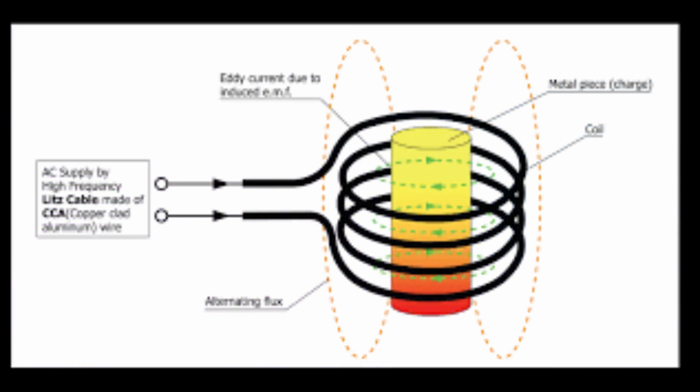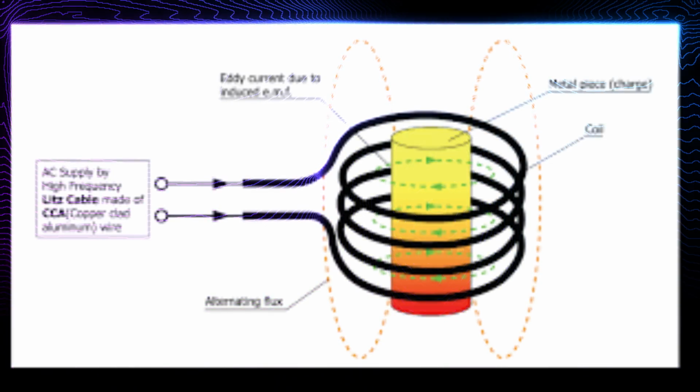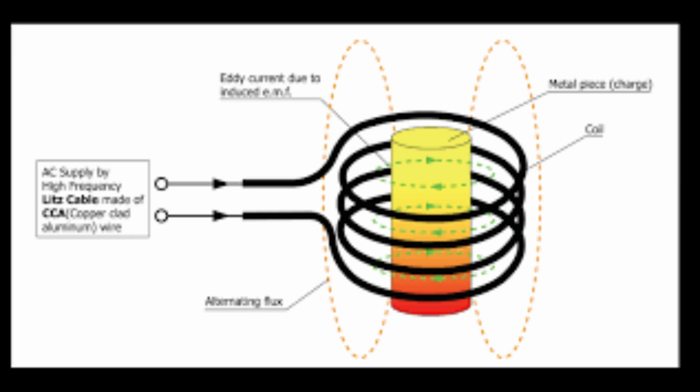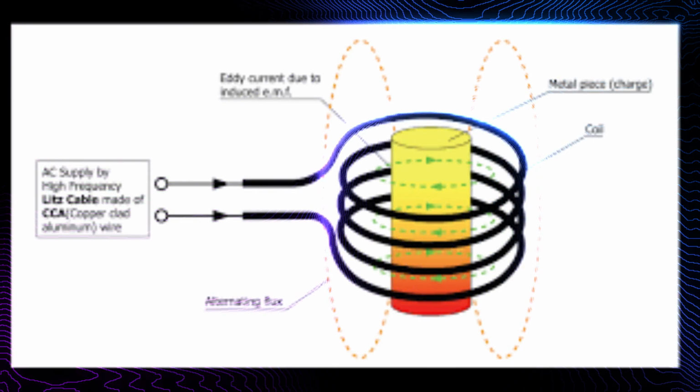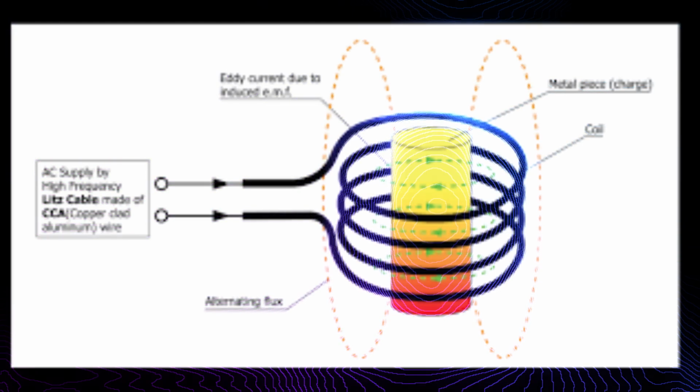Since only 4.8 volts is needed to push the current through the wire resistance of the inductor, the remainder of the 120 volts is used to overcome the coil's induced voltage of 119.9 volts.